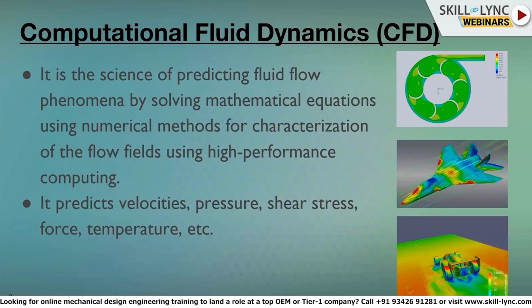There are different discretization methods you might be aware of, like finite volume, finite difference, finite element, or lattice Boltzmann method, etc. What is common in all these methodologies is that the partial differential equation, that is the Navier-Stokes equation, is approximated as an algebraic equation and solved numerically. It is an iterative process using high performance computing.